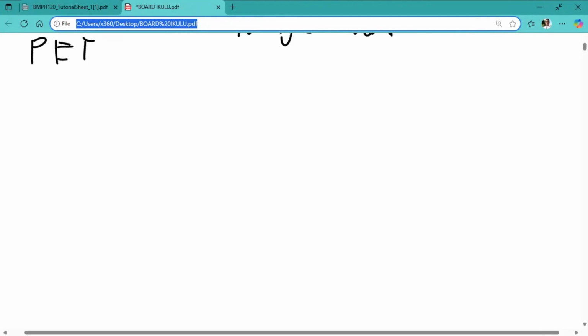The other one is polytetrafluoroethylene. This one mostly has a Young's modulus of 400 to 800 megapascals, which is similar to, and slightly less than, the natural ligament that we've calculated.